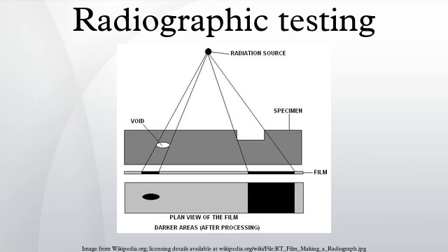Radiographic testing. X and gamma ray techniques with film. ISO 17636-2, non-destructive testing of welds. Radiographic testing. X and gamma ray techniques with digital detectors. ISO 19232, non-destructive testing, image quality of radiographs. European Committee for Standardization: EN 444, non-destructive testing. General principles for the radiographic examination of metallic materials using X-rays and gamma rays.